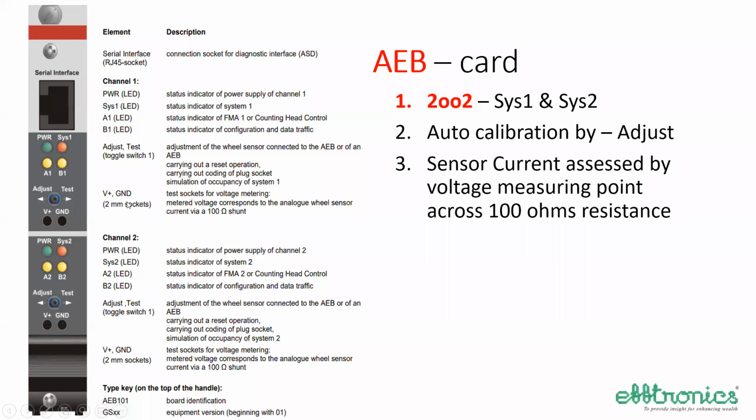Calibration. If you remember the initial days, or even some of the present axle counters, the value of the sensed voltage reaching the central place had to be adjusted by operating a potentiometer with a screwdriver or whatever. Now that has been automated, or semi-automated, after installation of the wheel detection unit.